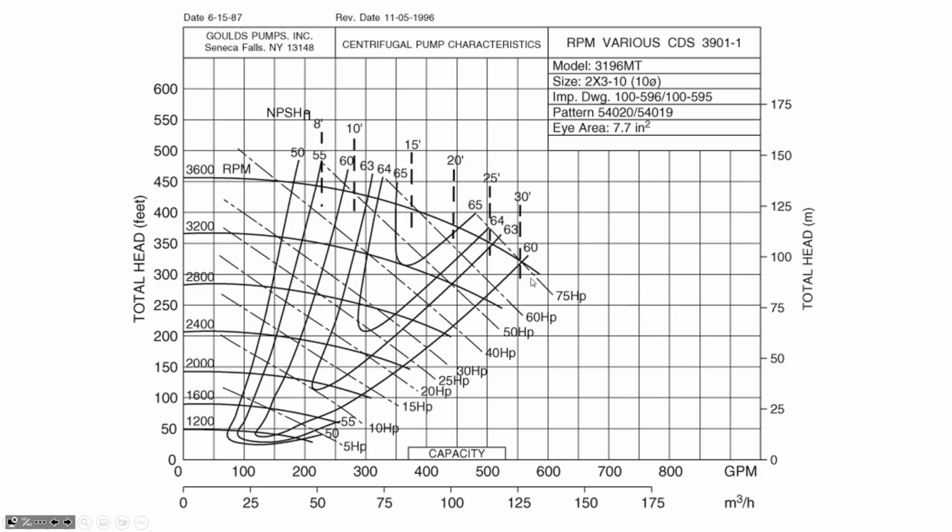So the question is, is there that much suction head that's available? Because if not, it's going to cavitate. So the risk of cavitation increases the faster the pump is operating. As you put more water through the pump at a higher flow rate, the liquid velocities in the pump are higher, and therefore the pressure on the suction side of the pump is lower.